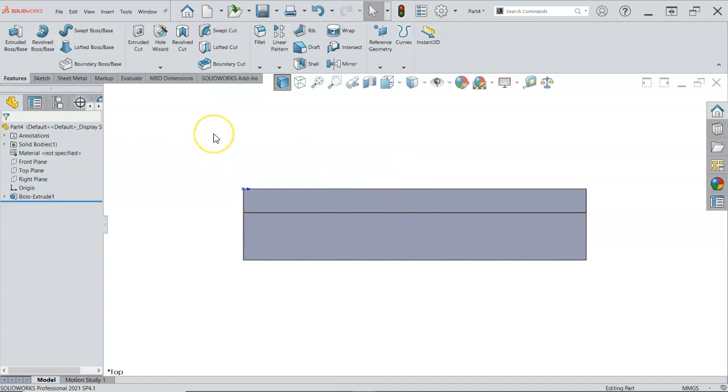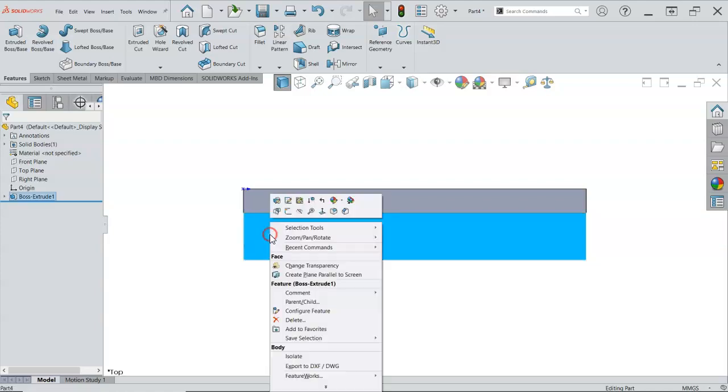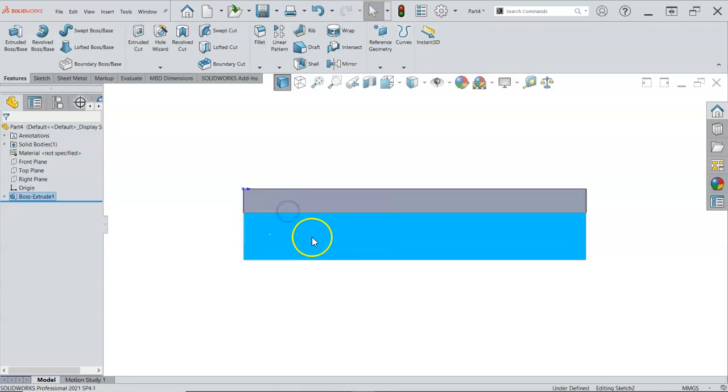All right, so for the first sketch, I have to decide if I want to make this a hole wizard item or a standard sketch. So this being our first go around, we'll compare the hole wizard versus the cut extrude feature. To get us going, we'll just go with the cut extrude. So sketch.